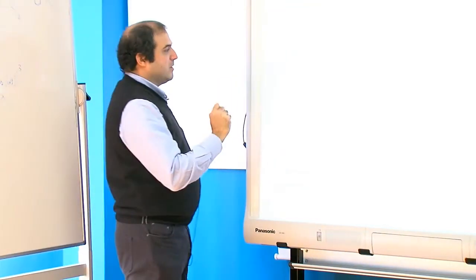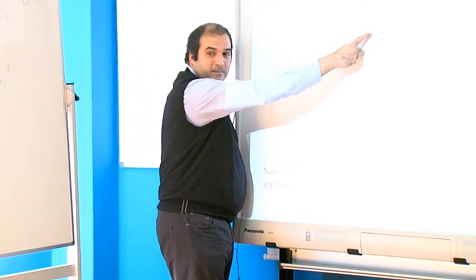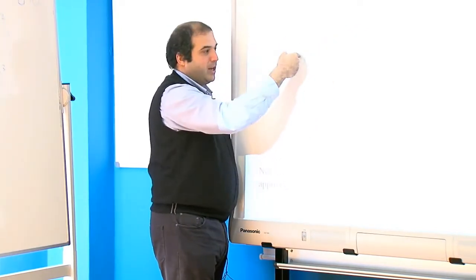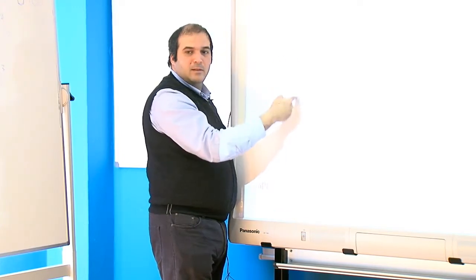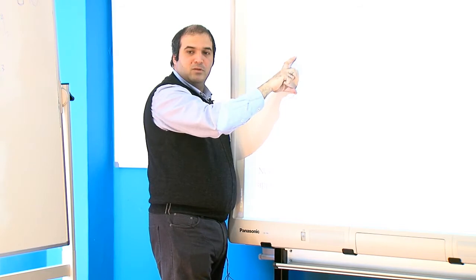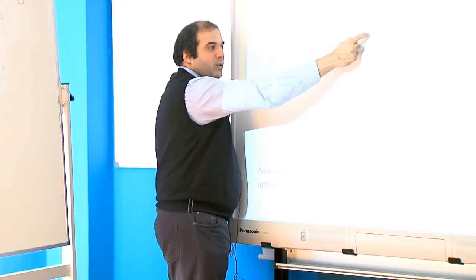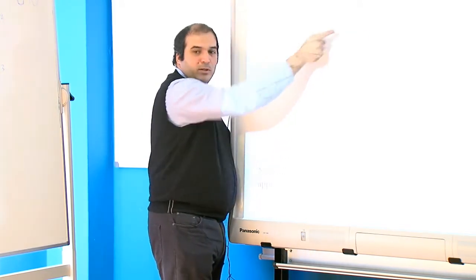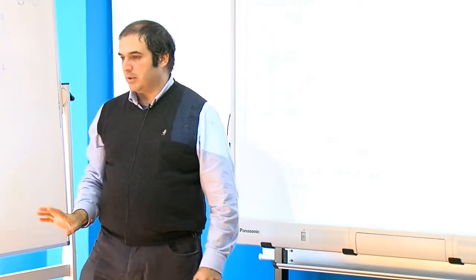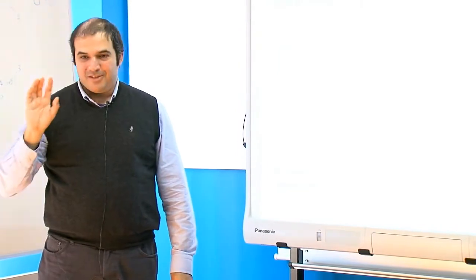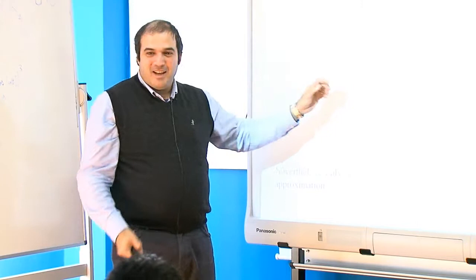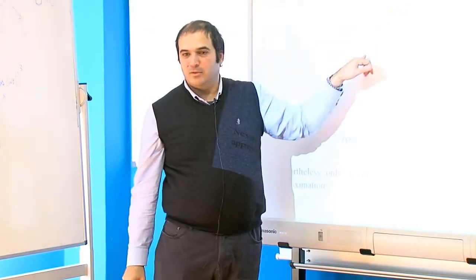It's very important because since I know this point, if I know this output power, these are two lines, so I can know exactly what is the relationship between my fundamental and the third order distortion, you see? So I only need to know one point and another point, and I can extrapolate this one. So this is why IP3 is very, very important. But it doesn't exist in the sense that I cannot go there and measure it. I can only extrapolate from a curve like this.